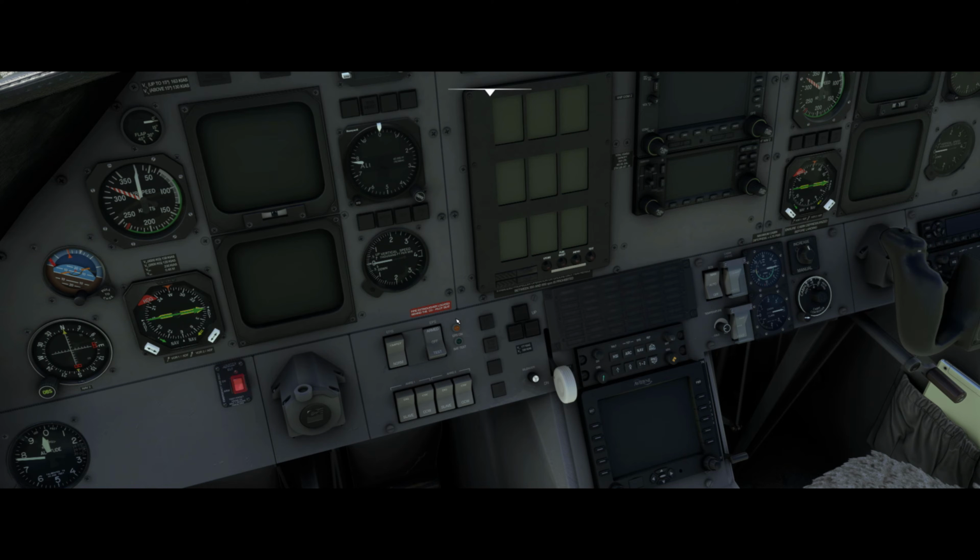With the rest of the electrical system off in the airplane, we want this EPS light to be illuminated to tell us that the EPS is working, that the EPS will automatically come online when the rest of the electrical system is turned off or has failed in the airplane. So this isn't modeled correctly in the sim, but that's how that switch works in real life.